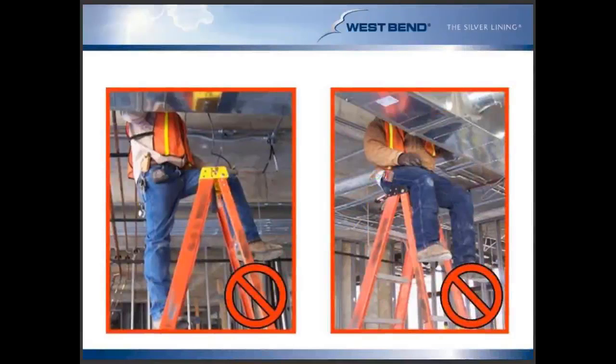This is obviously the bad. This is what we don't want to see when we go out to our job sites and into our shops, is seeing employees use a step ladder improperly. On the picture to the left, you can see the employee straddling it with their foot on one of the cross braces on the back side of the ladder. Those are not intended to be used as steps, and obviously we shouldn't extend our center of gravity above the top of that step ladder in fear that it could tip over, and obviously not sit on top of the actual ladder itself. These are both things that, if you refer to those labels and manufacturers' instructions, they will tell you not to do.